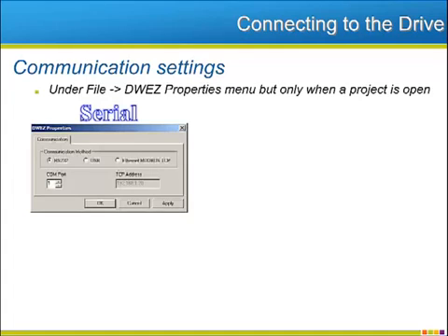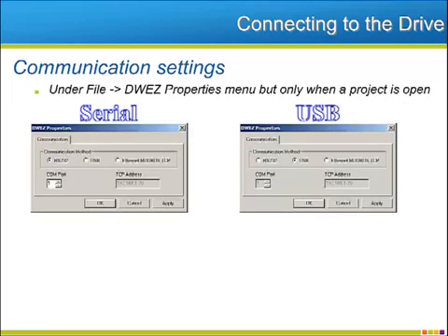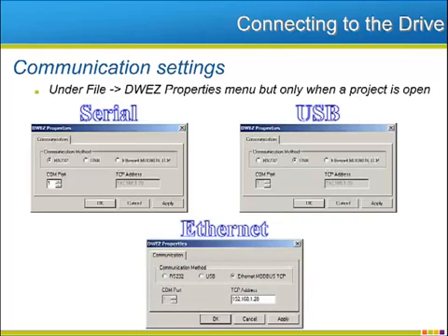Whatever your preferred method, open Device Manager. Go down to Ports, and determine which one you are connected to. The USB selection is self-detecting and does not require you to choose a specific port. When choosing Ethernet, you must provide the IP address of the option card.